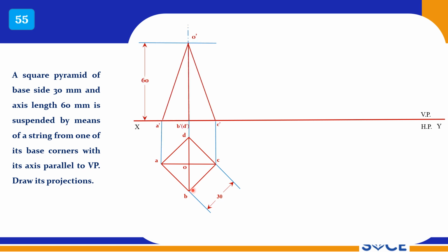It is a simple front view. So there is no change in the simple position. So now you have to do this small calculation. From the base, the CG, center of gravity, will be lying at a height of one fourth of the solid height, right? So from the base, you have to calculate 60 by 4, that is 15 mm. From the base at 15 mm, you will have CG, right?